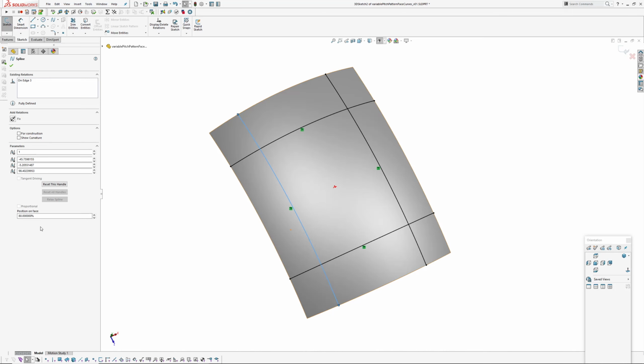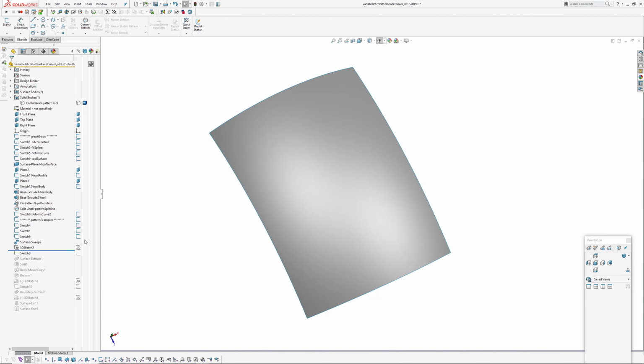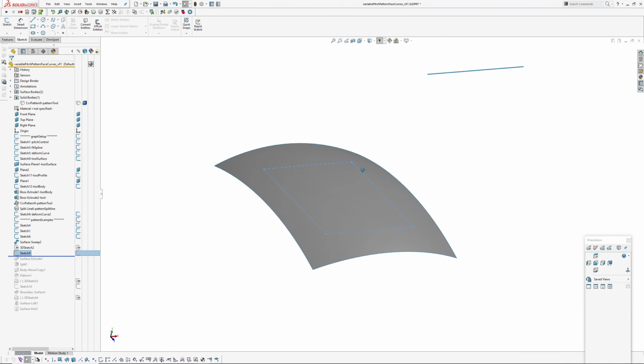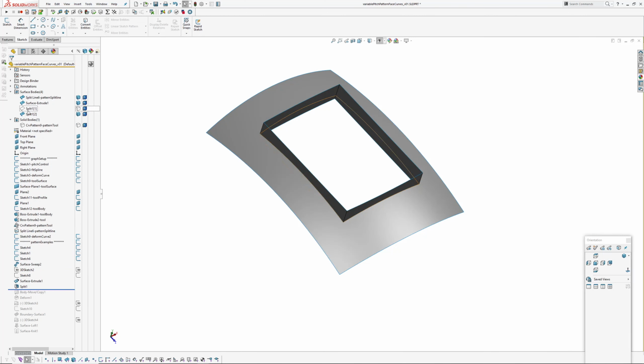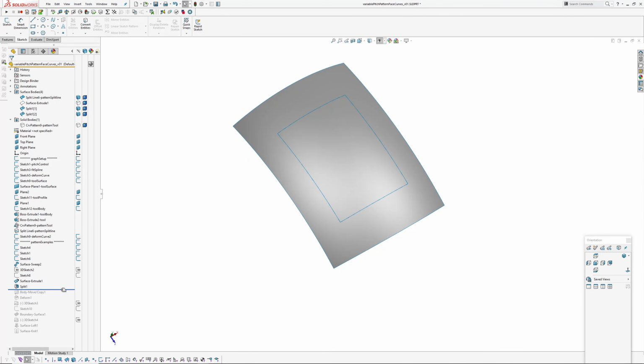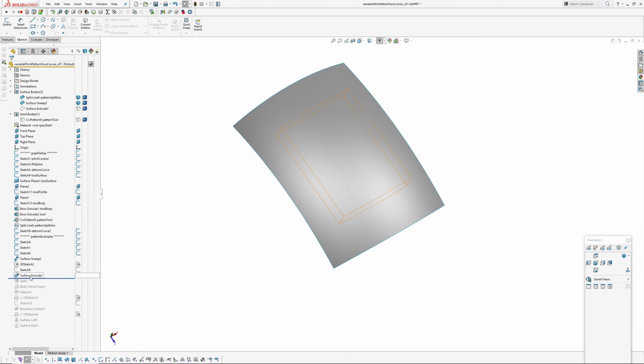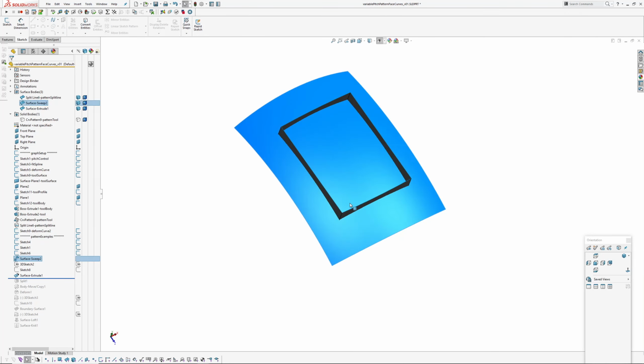And then one over there, and then I have converted those entities into a 2D sketch, made a surface extrude, and then I've split this face into 2 bits using the split tool. So if I go back up here and show the other half. If you haven't used the split tool before with a surface, before the split tool was there, you'd make 2 copies of this and trim it twice.